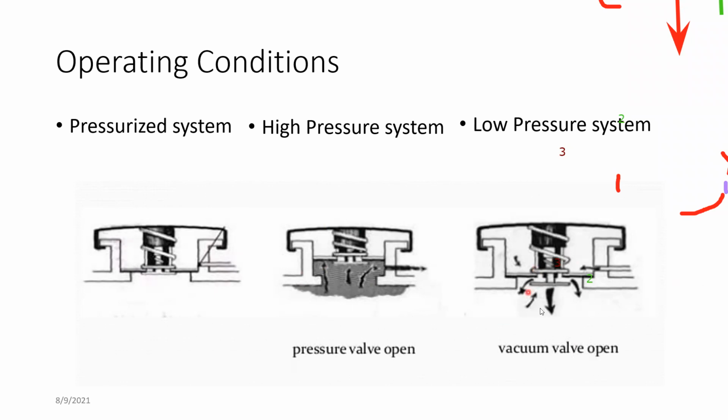So when it is actually lower, this vacuum valve starts to open. When the pressure is dropping, this vacuum valve opens again. Since there's a vacuum inside, the coolant from outside, or from your reservoir tank, will be sucked inside, or absorbed inside, until it's reached the correct pressure again. Once it comes to the correct pressure, this will close again.